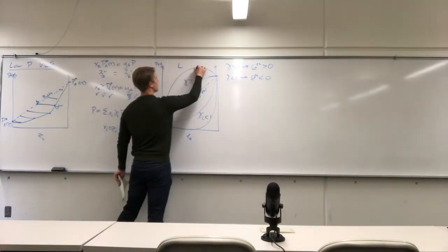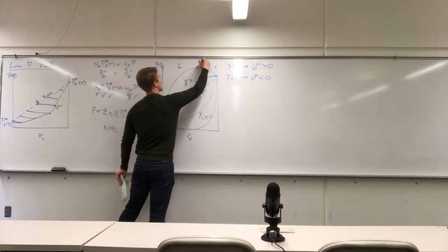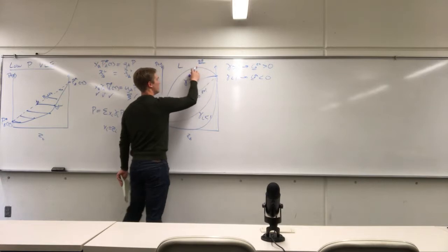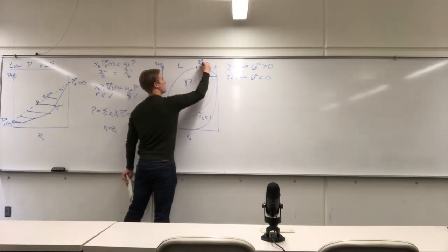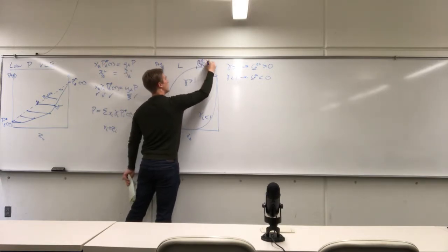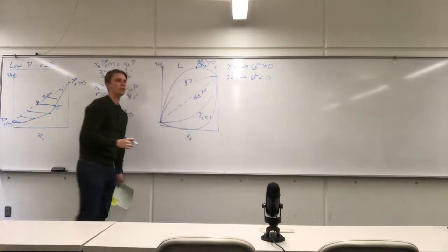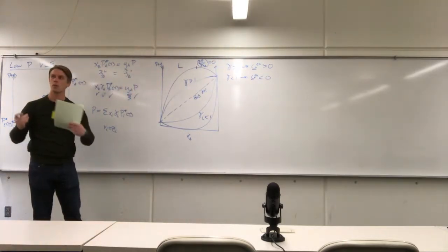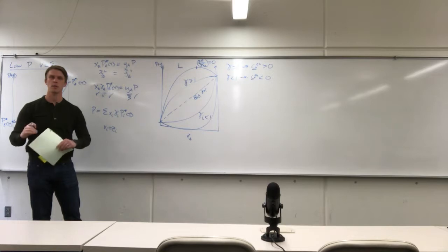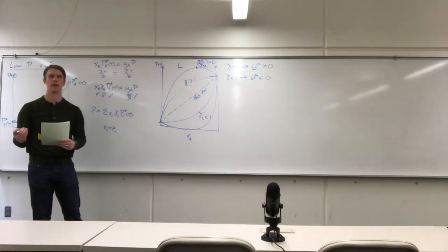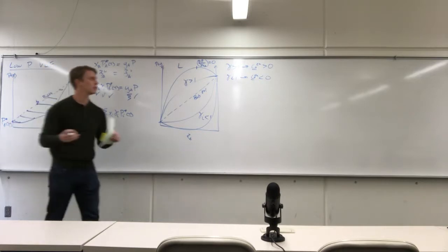And we find a position right here where we observe that the change in the pressure of the phase transition as a function of the mole fraction is equal to 0. So we reach a maxima or a minima in a PXY or a TXY diagram. Does anyone know what this causes? It's an azeotrope. It is an azeotrope.